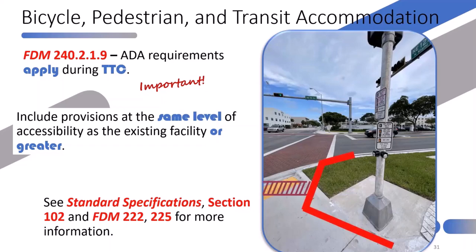In the picture on the screen, I've tried to indicate again that a little foresight to the configuration of the curb returns there, and we could have a much more substantively compliant solution for that curb ramp that aligns with the crossing direction.